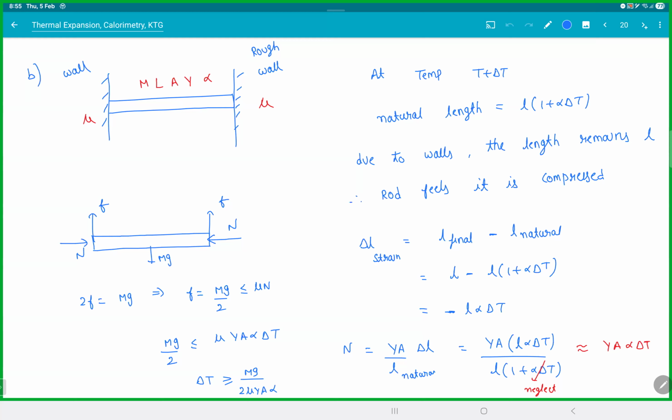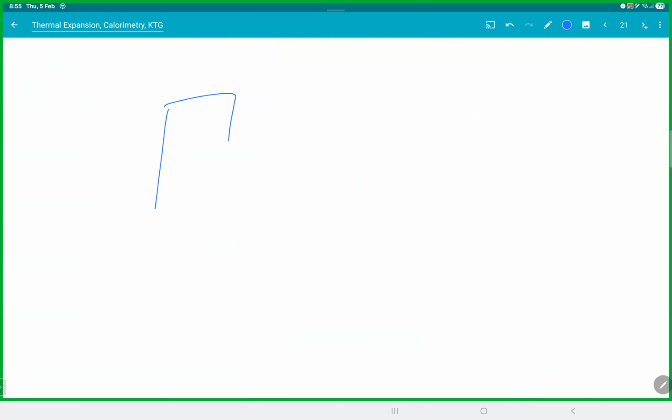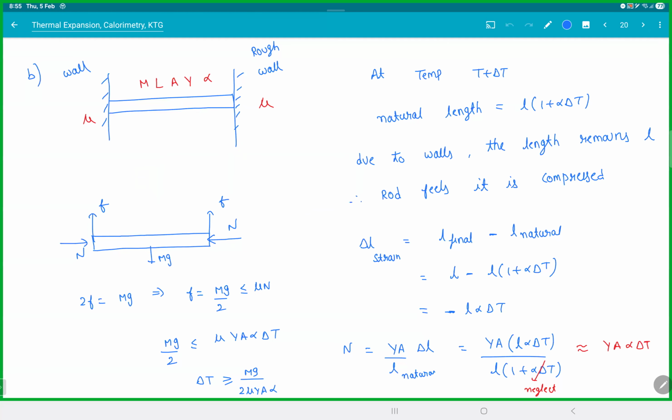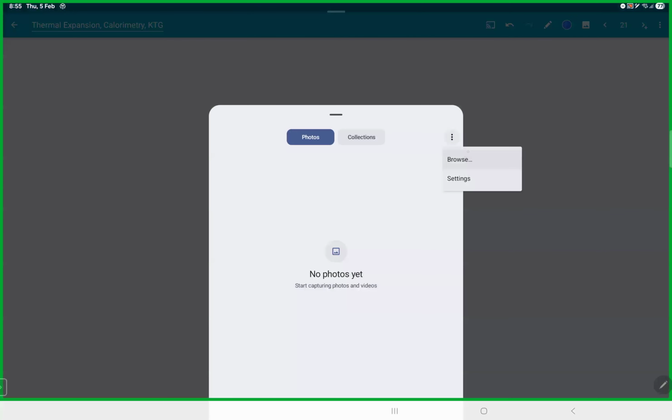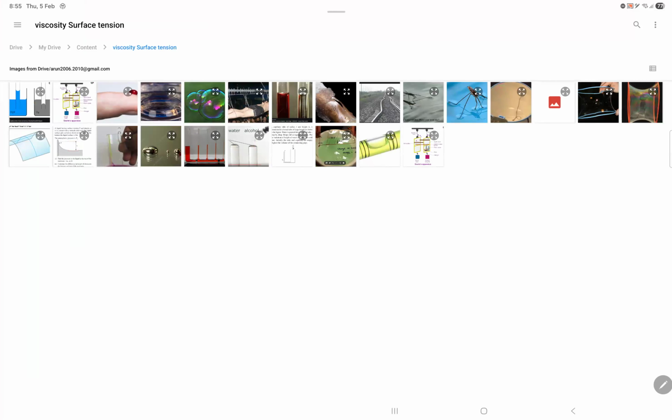And this thing can really be a lot of stress. Did you ever, when you go on a flyover, hear the tuck, tuck, tuck sound? When you look down on the road, you'll observe the flyover actually has sections, and there's a thin gap between the sections. That is because during summer, when the roads become really hot, they leave very tiny space between them to expand. If you don't leave that space, the sections will push each other and you get a lot of internal stress.